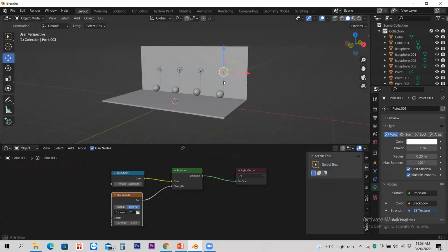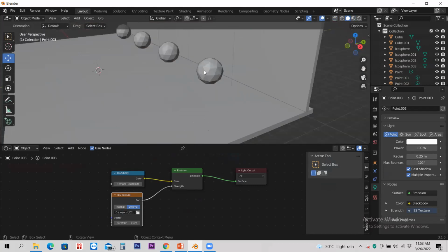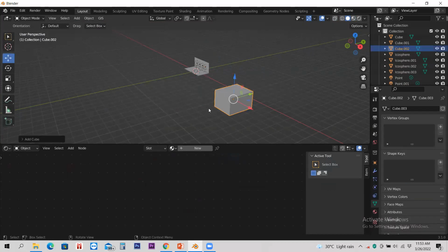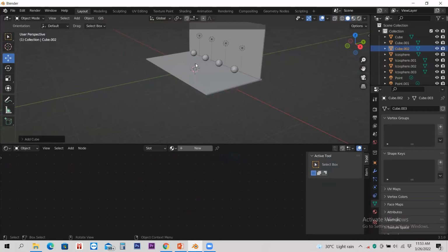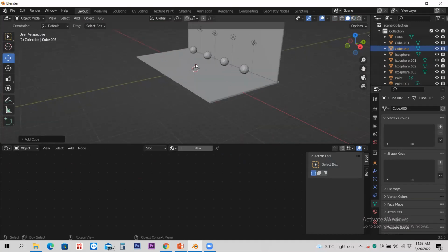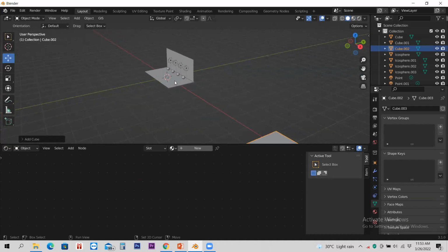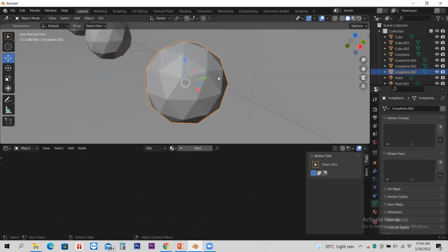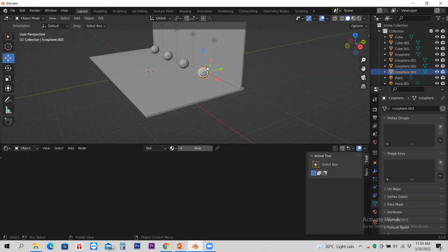Okay, I think Faisal, your question is this: when you have some big object here, sometimes you keep on zooming and it goes very slow, isn't it? The way to avoid that is to click an object in your field of view where you want to zoom in, and on your number pad, after 0, there is the dot sign. Just click the dot, it will zoom into that, and after that it's once again smooth.